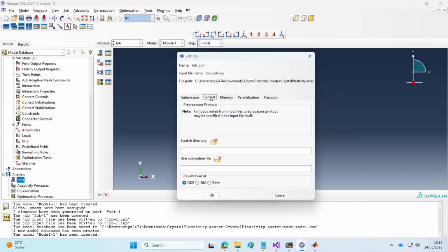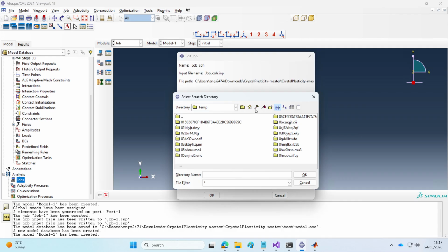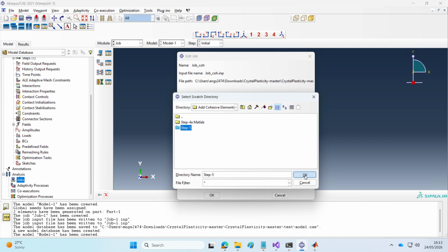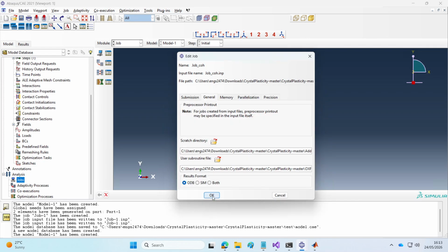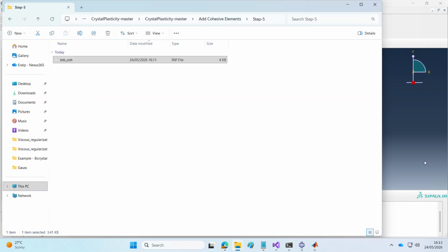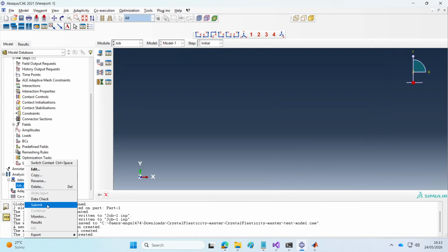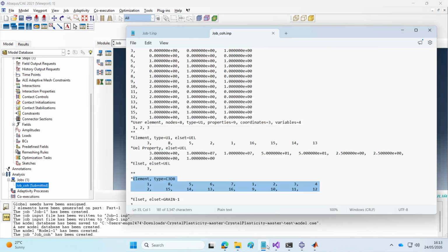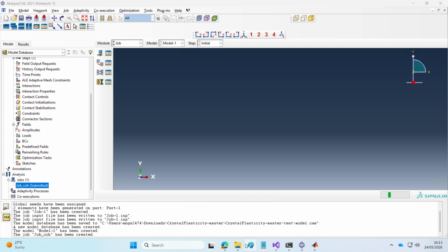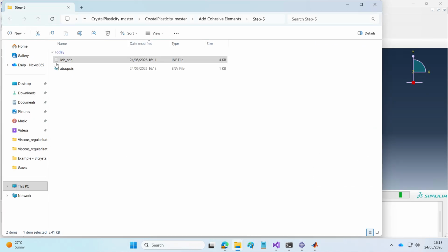Unfortunately, we won't be able to visualize anything. Setting the scratch directory and set the UMAT, point to the UMAT file, which is going to be the Oxford UMAT file. Okay, and that's it. And then just run it. Well, before submitting, we could have changed some other things, but let's have a look. Until it compiles, we still have time. So, okay.